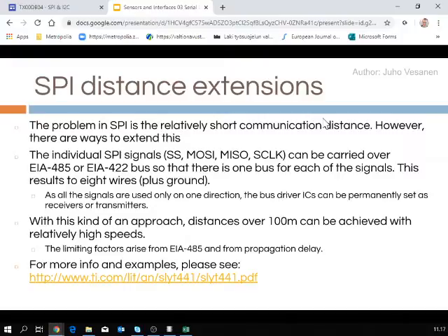They are just line buffers that are designed for paired wires, meaning the matched pairs. Matched pair lines, impedance matched lines, and distances of 100 meters or more. Easy. You just need to make sure that you don't get much reflection or too much attenuation on the line, meaning good impedance matching.